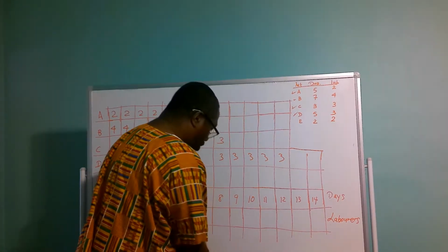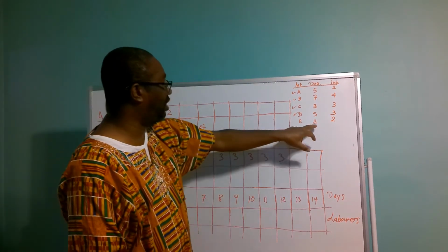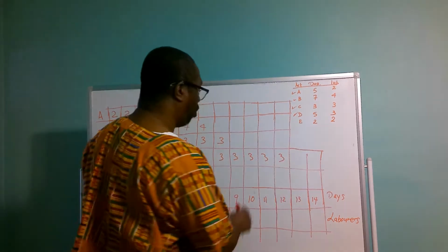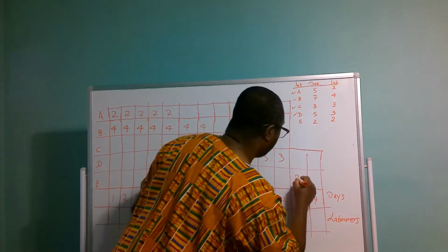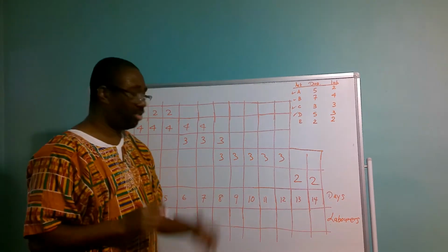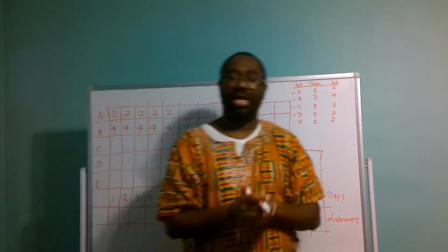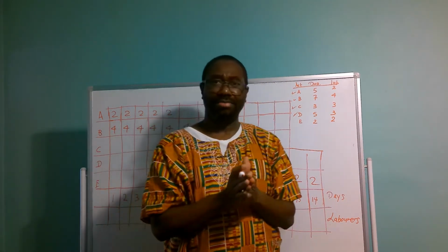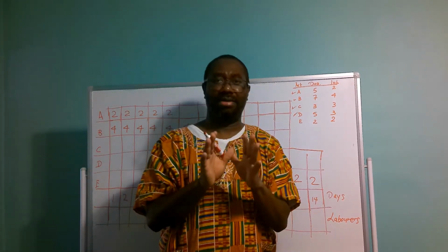So go back here now. So we move to the 13th day for activity E, and activity E has a duration of 2 days with 2 laborers for each day. So we're going to have activity E 2 times, so 2 and 2. So you see, it comes back to our 14 days. So now we can total the amount of laborers for each particular day, right?